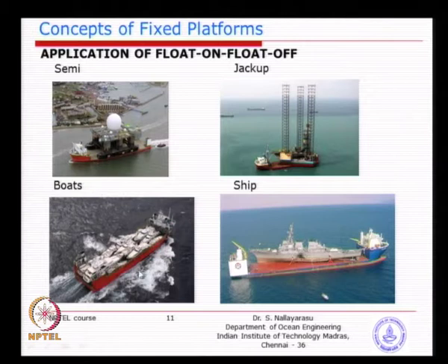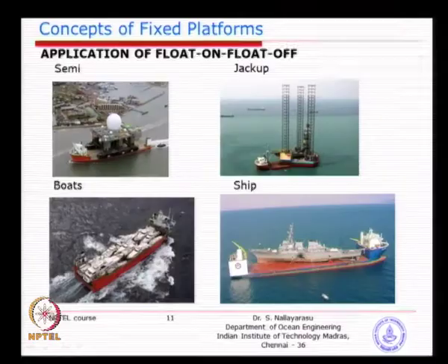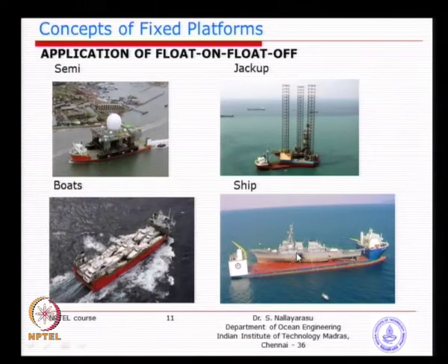You see here so many small boats being transported by a bigger ship, again float on, float off, because the mother vessel will submerge. Otherwise, you would end up lifting and putting them in, which may not be possible, because either the structure is too big and too heavy to lift, or when you do lifting, these ships or boats may not be able to take the stresses, because they were not designed for it. You see here another ship being transported on another bigger ship. So, this kind of idea uses float on, float off in water most of the time.